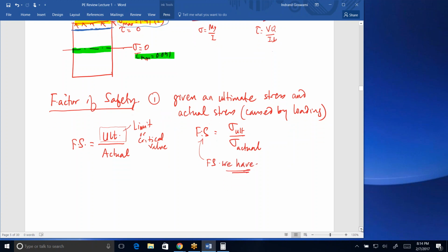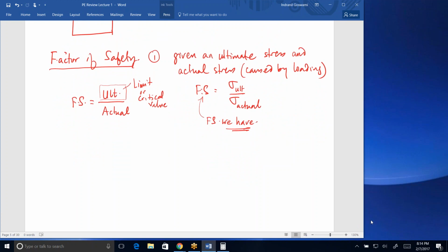Right? It may be acceptable or unacceptable. For example, for retaining walls, the typical desired factor of safety against horizontal sliding, friction on the subbase and so on, is typically around 1.5 or 2, right? Now, if I have a 1.2, we have a safe situation, but not an acceptable situation because we haven't met that threshold of 1.5 or 2, whatever the code said, right? But that's what we have. Given the loads and given the capacity of the soil to resist friction below the footing of the retaining wall, that's what we have.